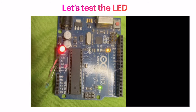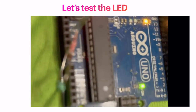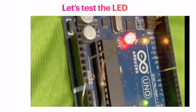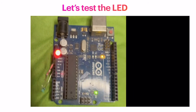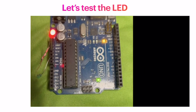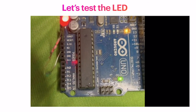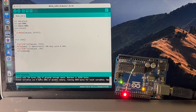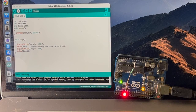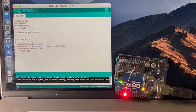The first thing to do is to test. We can do this by connecting ground and the 5 volt supply on your Arduino board. This 5 volt supply is used for connecting an external circuit, and you can see it is working nicely. So we can go ahead with our experiment by connecting it between pin 4 and the ground. Once the code is written, this is how it looks, and we can flash it onto the board using this button, and you can see the data being transferred.